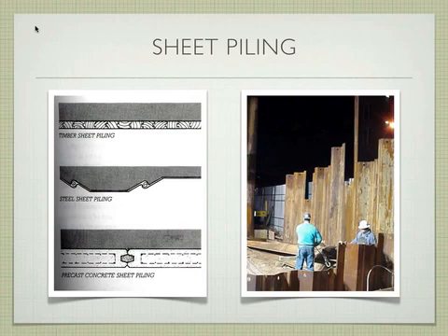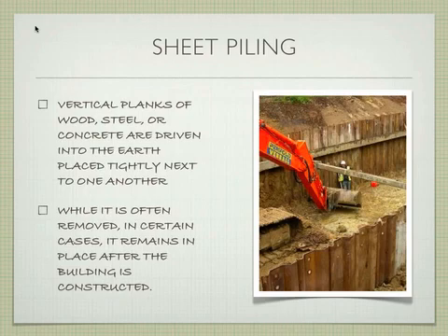Does that make sense? It's a slightly different method, but this can be an efficient way of doing it because you're not dealing with the timber. You just ram these sheet piles in, then you dig out the center. There's not much else required, which is nice. So it's easy. This is very common if they're working on a sewer system or something like that. It can be made out of timber and it can be made out of concrete, but the most common is going to be this kind of sheet piling here.